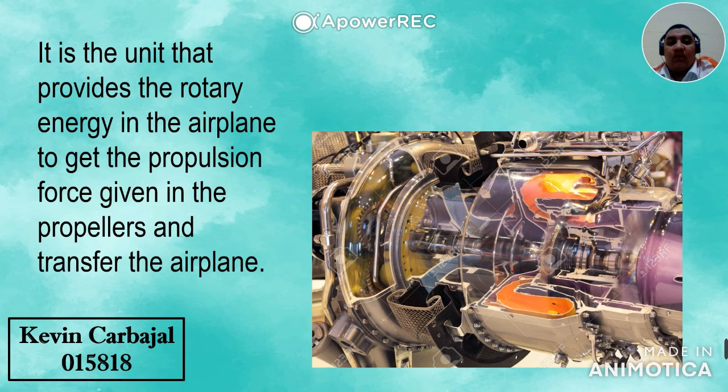That unit and those components are used to induce and convert the fluid-air mixture into energy, and to transmit power to the propeller shaft and accessory units. This covers reports related to the reduction gear, combination gearbox, propeller drive shaft, and helicopter rotor shaft, which are used to transfer power from turboprop and turboshaft engines to the propeller or rotor of a helicopter.